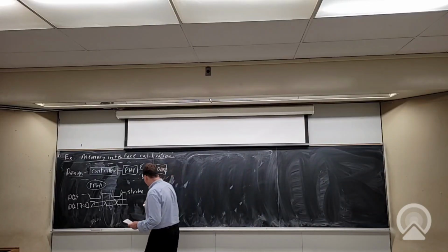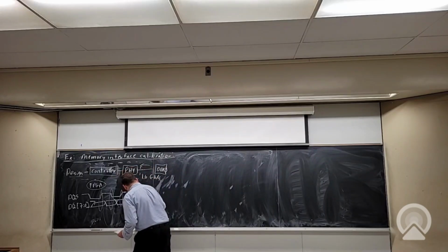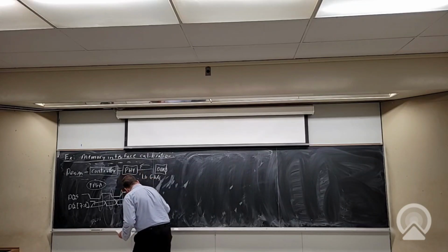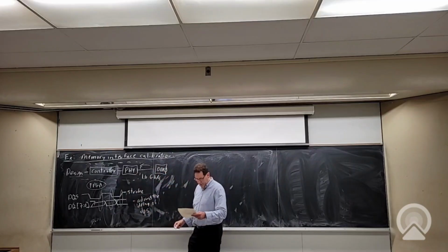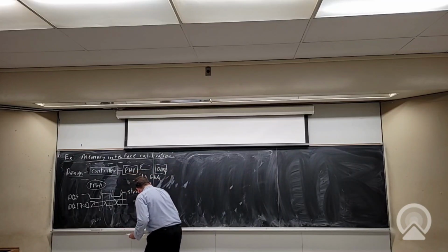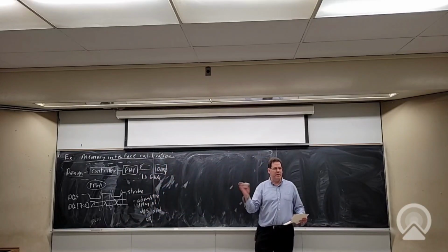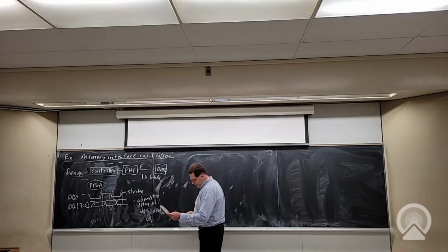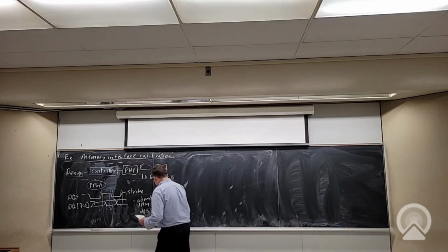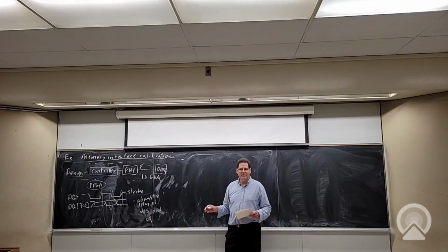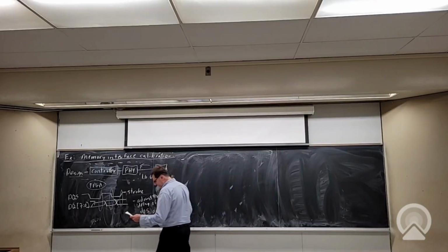So what you have to do is calibrate. You have to adjust the delay of basically every DQS, and for a 64-bit interface, we'd actually have 8 of those, and every DQ bit, until it works. We can reliably send data, write it, read it back, etc. Does that make sense? Hopefully you're with me.